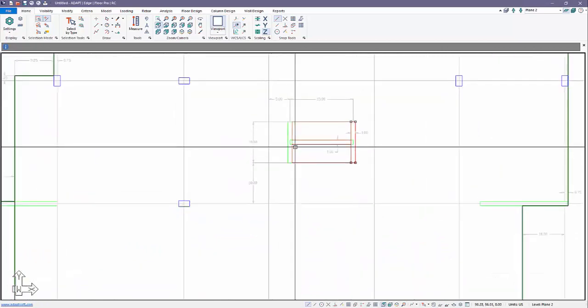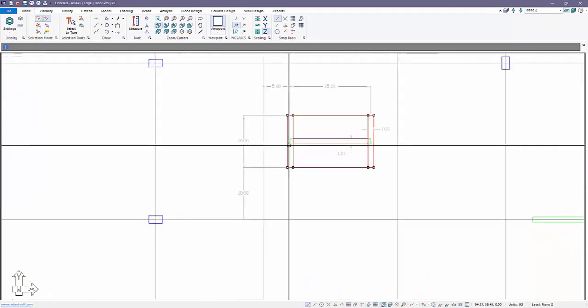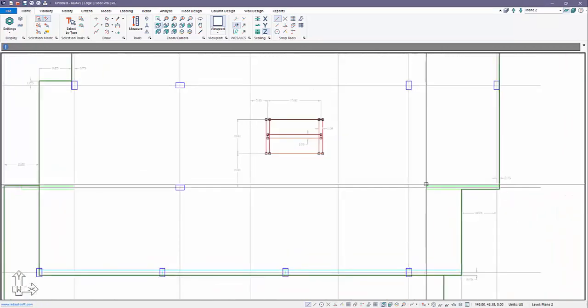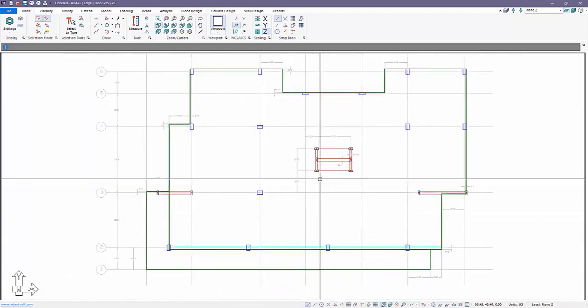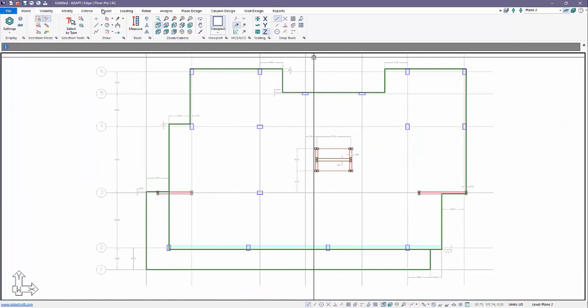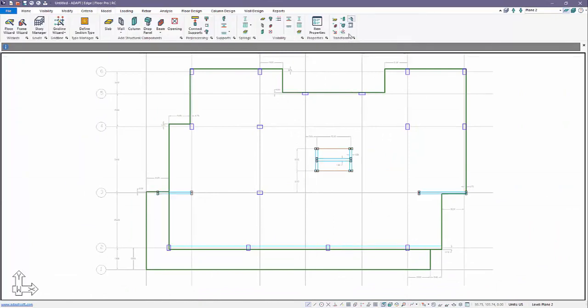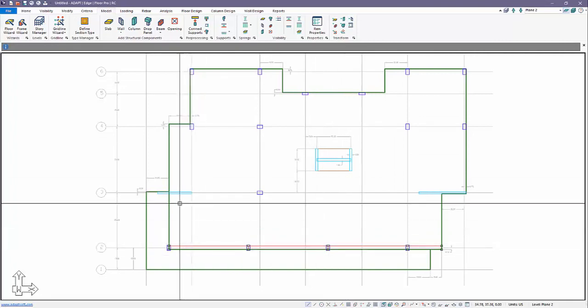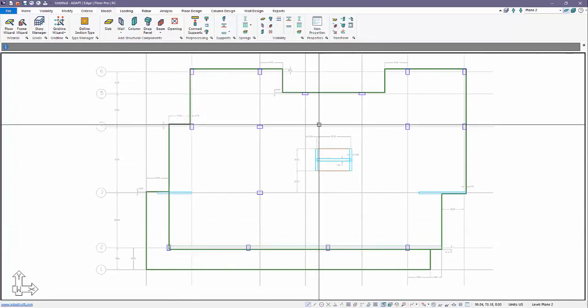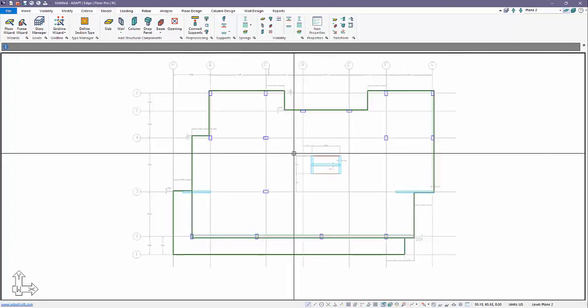and now I'm going to go ahead and select my walls for the model, and we'll transform those single walls into structural walls. Okay, so we'll go over here to model again. Those are transformed to walls, and the last thing I have are polygons representing my beams, and we'll transform those to beams. So now we're left with a structural model.